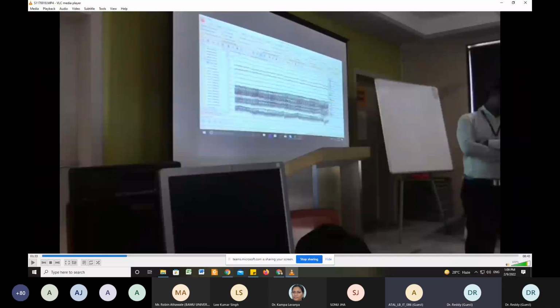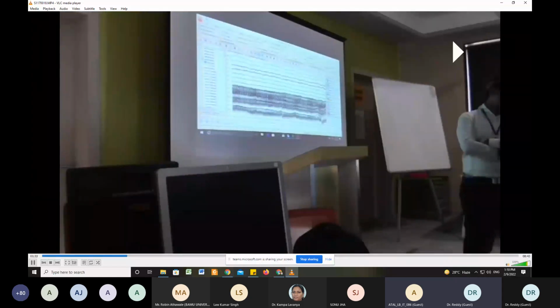Are you following me? Then what happens in Brain Vision Analyzer, in the same page which is open, at the top there is something called transformations. There is a filters option. You have to select from a lot of filters: low pass, high pass, and band pass filters. You select one, then give the parameters, the threshold values. Then you see what will happen to the same EEG signals. Just wait for a minute.